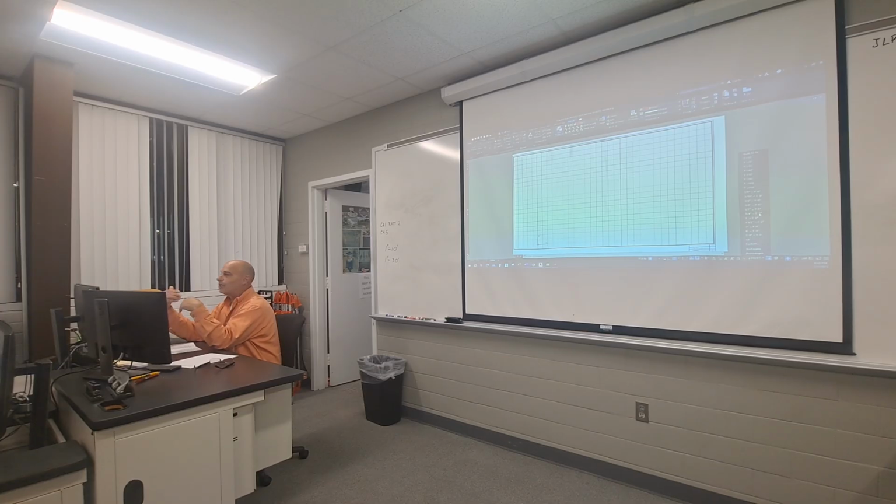If I were to go home and start working on a project tonight, and I open up my master drawing for architectural or something else that I'm drawing, my structural steel border, they've already got the scales and everything manipulated in here. So all of those scales that I deleted that you don't see on this menu, those ratio scales that I'm not gonna use, I took them off. I didn't affect the software, I didn't affect any other drawings, I just took them off this menu in this drawing alone. And then I went through and I added my engineer scales for my civil work.